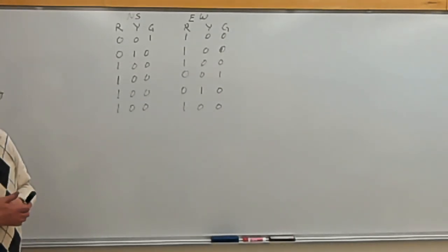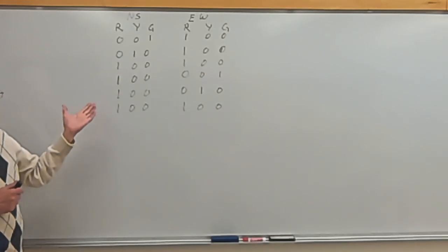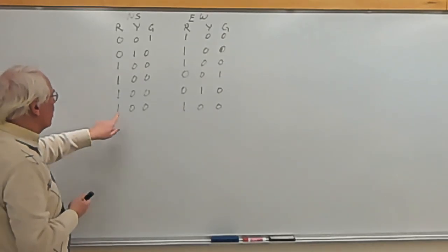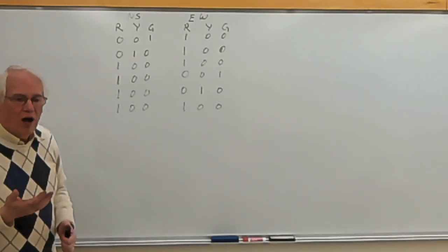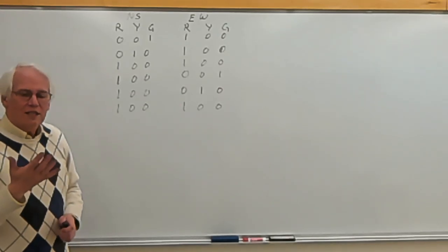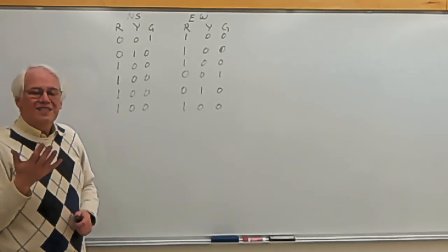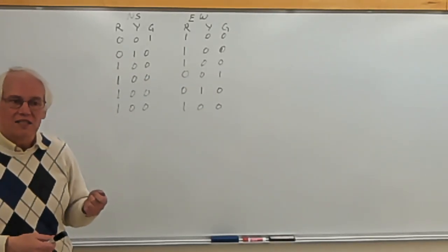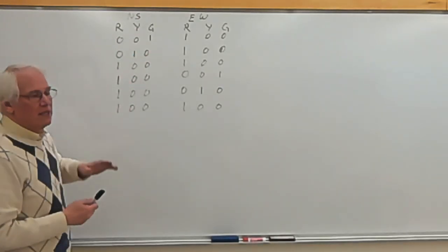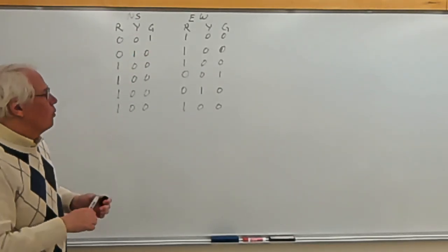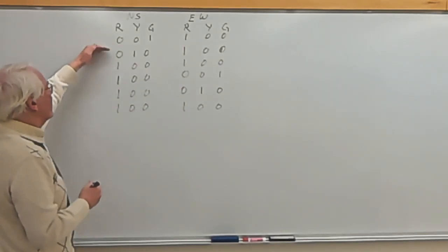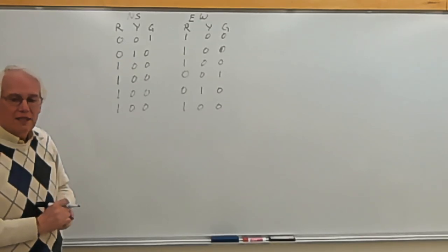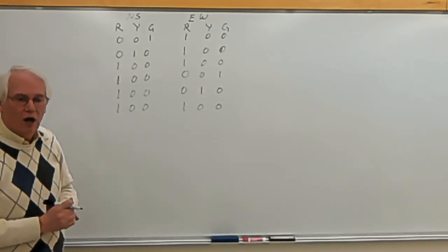And one of the other signs that we don't need this much information, that there's redundant information in this system, is that we've got 6 bits to drive these 6 lights. 6 bits can handle 64 possible states, and yet we're only using 6 states. Clearly there must be some simpler way of doing this. So what we can do is to separate the information about the state from the information about which light is turned on and which light is turned off.